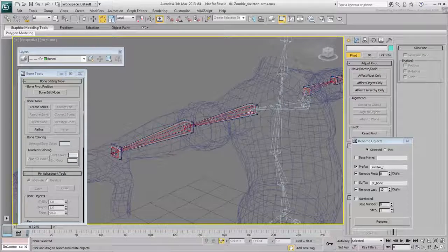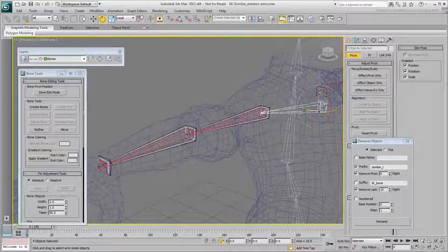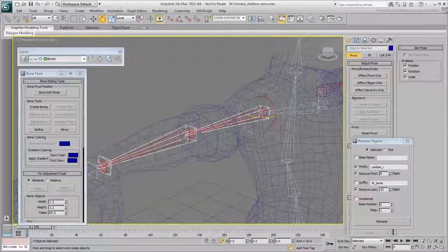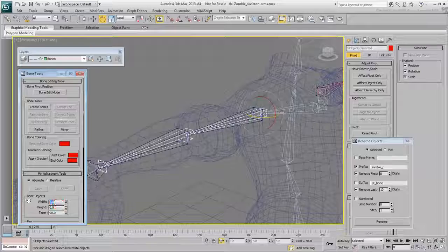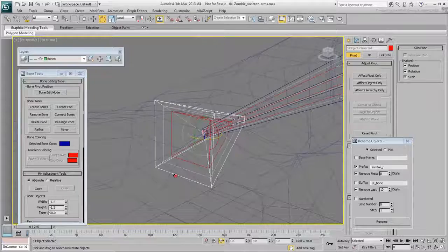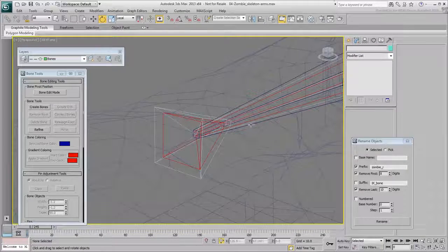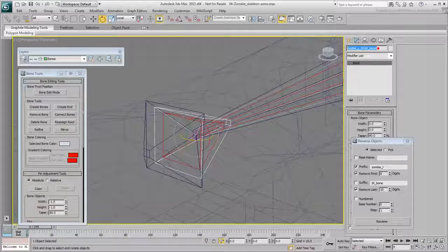Do them one chain at a time, as the main chain and the IKFK chains have different sizes. Lastly, you'll need to recreate the nubs. Address them one at a time. Make sure you copy the nub name to memory first, so you can paste that name to the newly created nub.